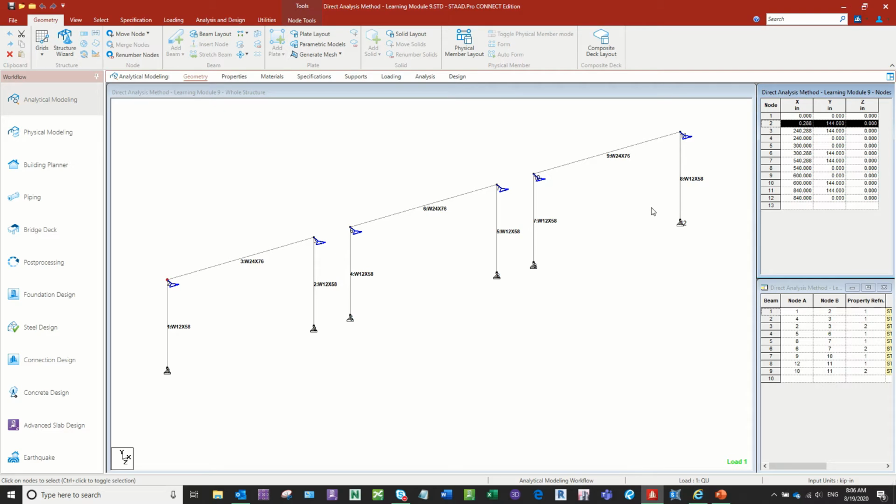So that's a little bit over a quarter of an inch of displacement over 12 feet, and that's what's allowed by the Code of Standard Practice in terms of erection tolerance. These nodes are modeled such that the structure is in its skewed position, and that's what the first model is about.